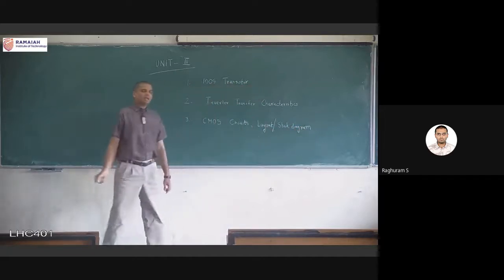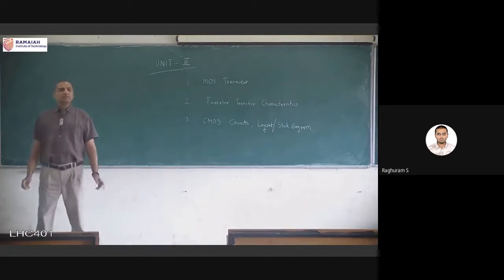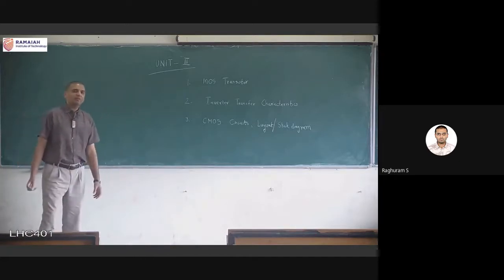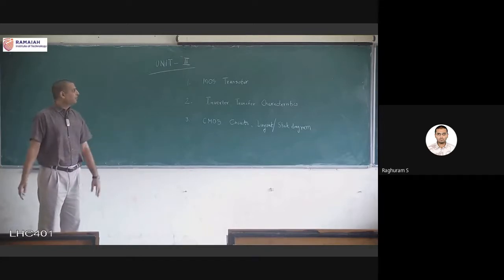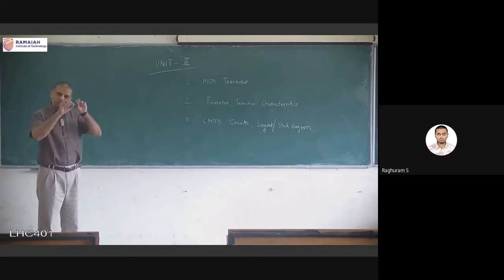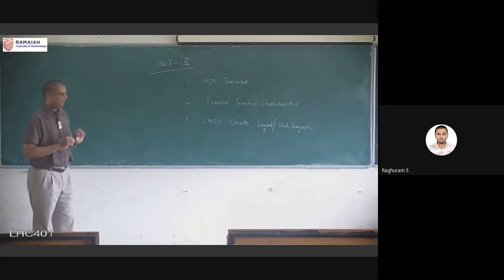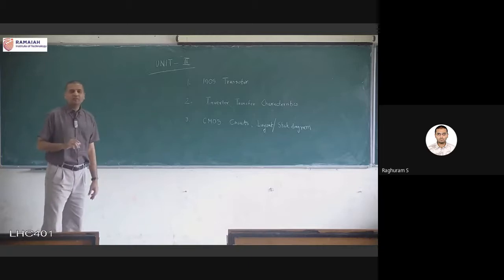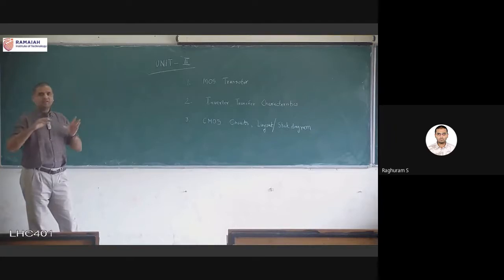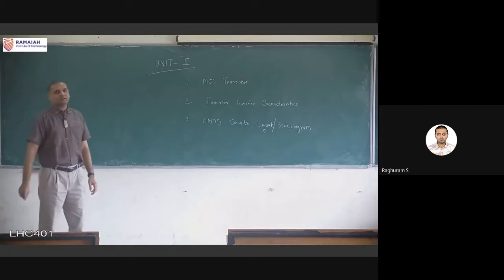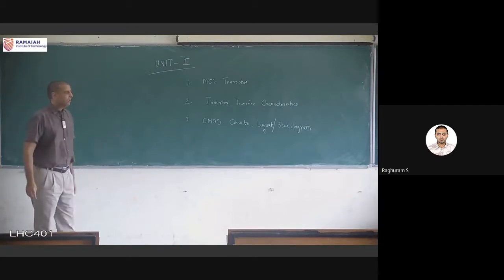layout or stick diagram. Both are very similar to each other, but layout we have seen. Layout is the final output of the fabrication process. For simple circuits that we will see, we will also see how to draw the layout by hand using a scale and pencil. And similar to layout is stick diagram. In layout, every wire, every transistor has to be in terms of sizes. In stick diagram, it is a simpler representation. We will just represent it by a straight line. That is all. They're both equivalent to each other.